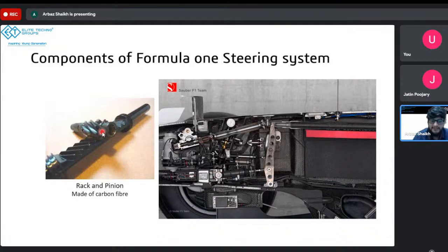There are two reasons for that. They want to reduce the steering weight, and they use helical teeth to avoid backlash. Remember, I told you about the backlash. To maintain constant contact, people also use helical gears. It's also very efficient to use helical gears to avoid the backlash.